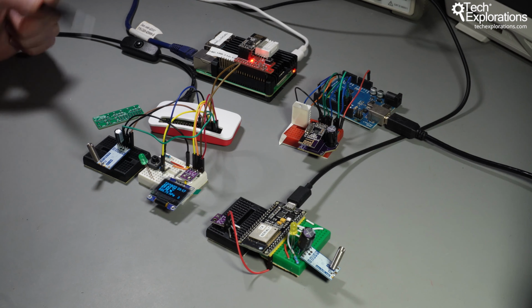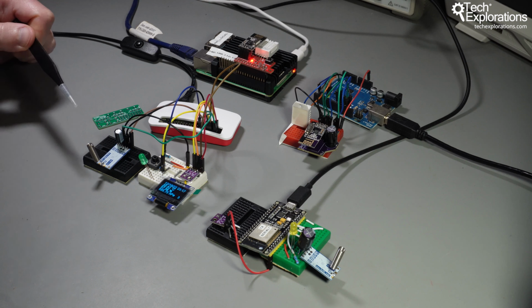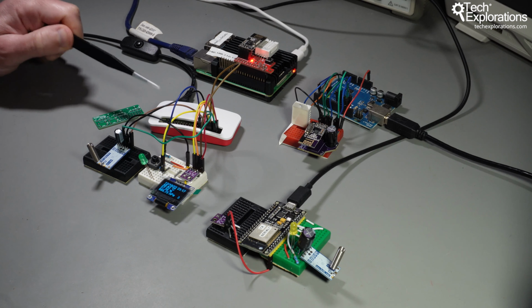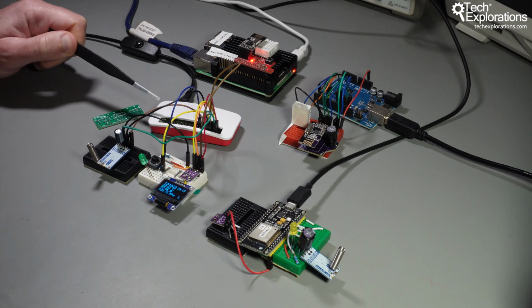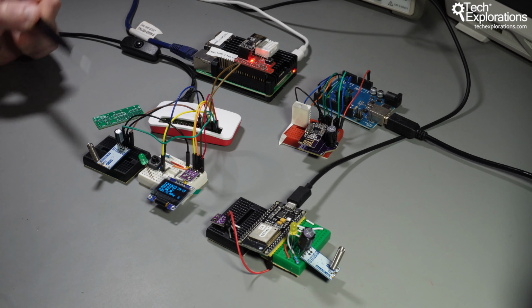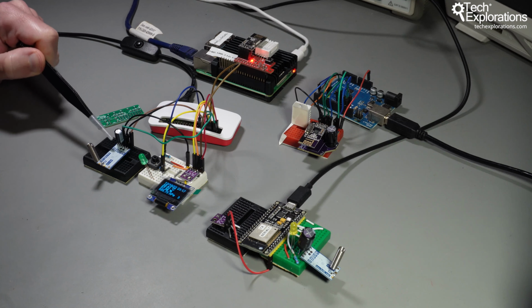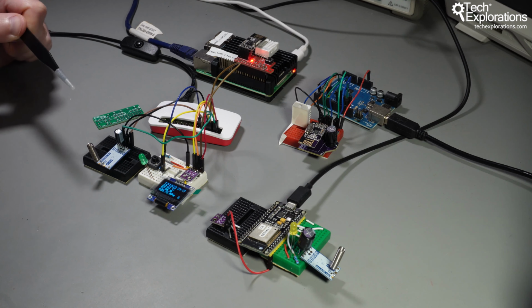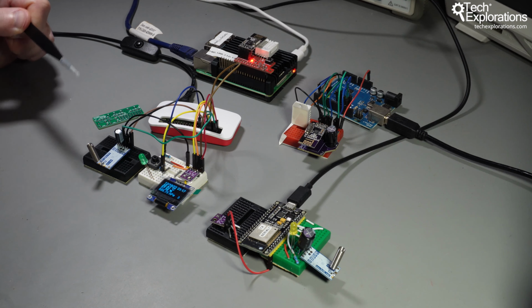Communications are easy. As I said, simply use the serial interface and you're good to go. There's nothing really that you need to compile or set up on the Raspberry Pi other than to turn on the UART interface. There's nothing to compile, no drivers. It's very simple. So this is a big plus of the application. It simplified things and increased reliability.